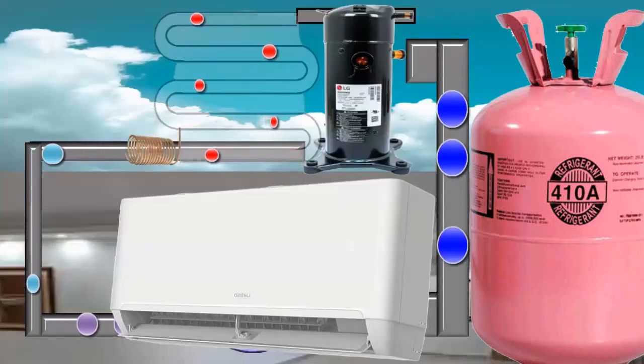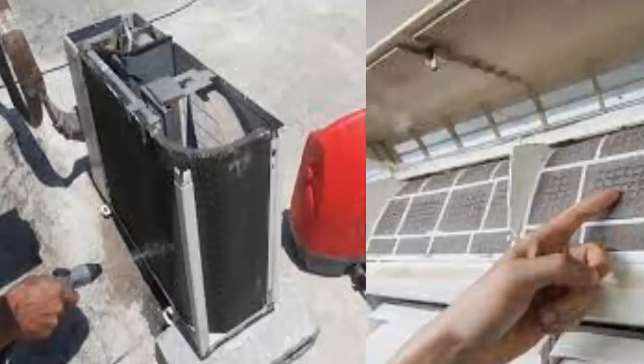To ensure a long service life of the equipment, it is essential to perform preventive maintenance, including cleaning the condenser of the outdoor unit, at least every 6 months.